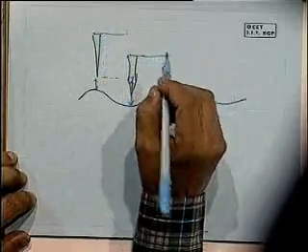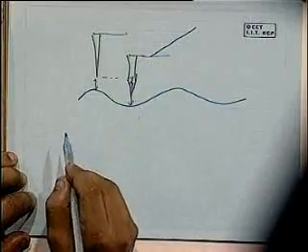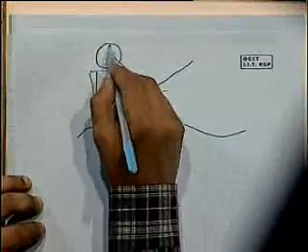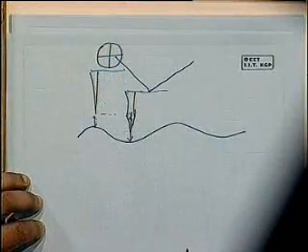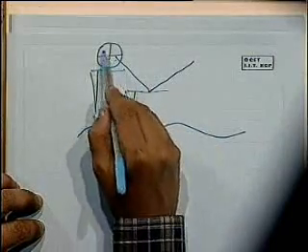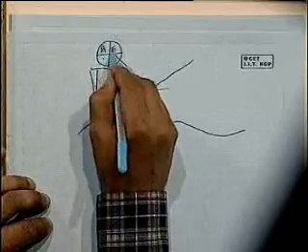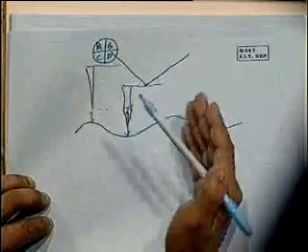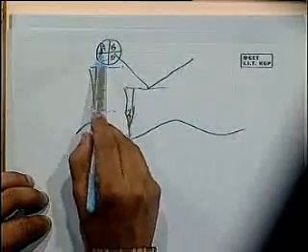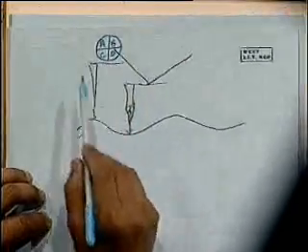It's a very fine tip, but the way they do that is by making use of a laser. A laser beam is deflected off of the top of this tip to a detector. That's called a 4-quadrant detector. And the light that is falling off will either be deflected to one of these 4 quadrants more or less. And each of those, so we have got A, B, C, D. And both the vertical deflection as well as horizontal deflections can be determined by summing up these or subtracting various segments. That's called a 4-quadrant detector.